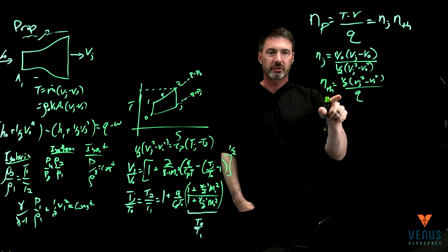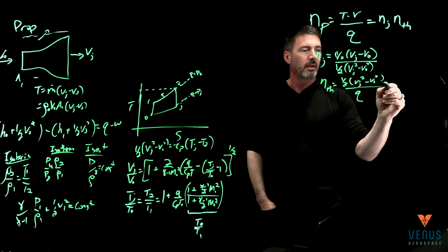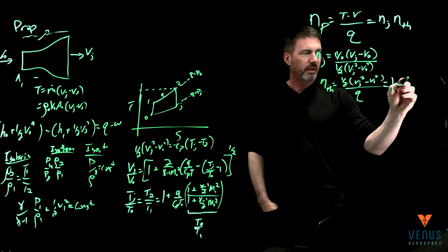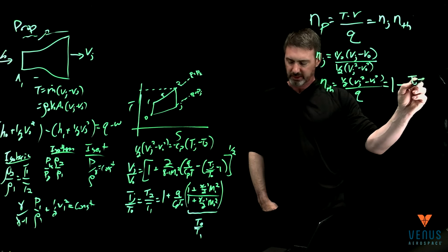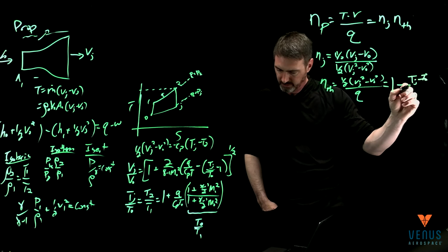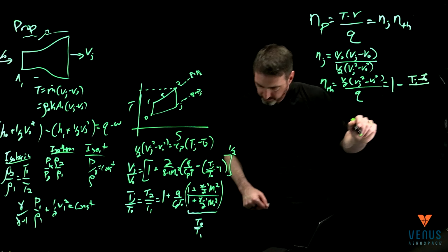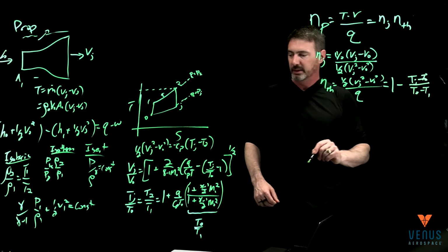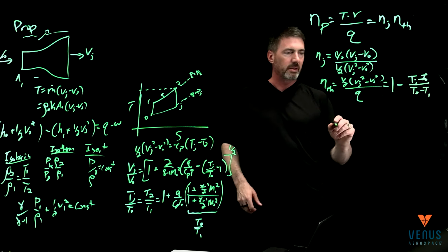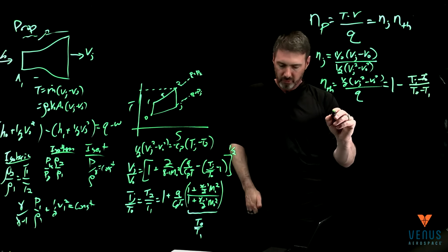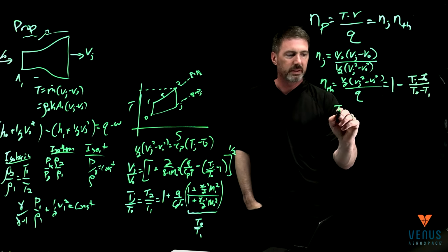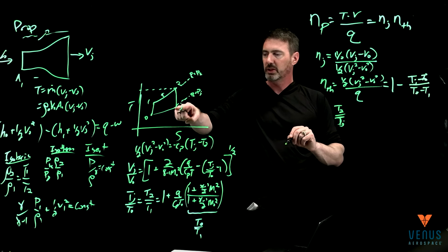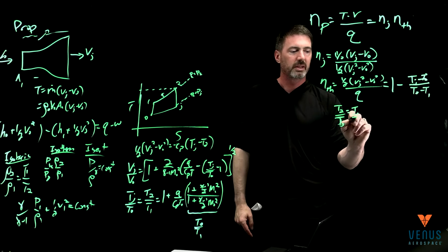Okay, so I'm going to play with this one first, and you can go work through and see that it is just T jet minus T0 over T2 minus T1. And keep in mind now the ratio of the temperature is the same, so I'm going to do one more thing here. We actually know that T2 over T jet is the same as T1 over T0.